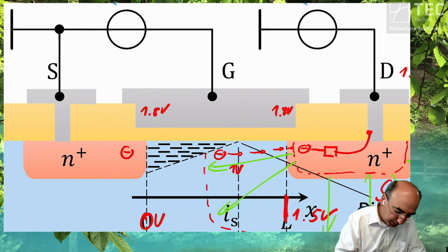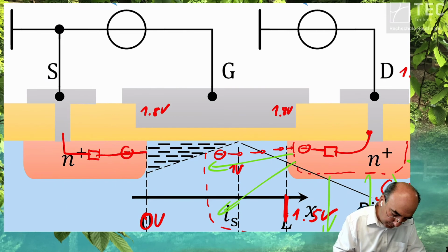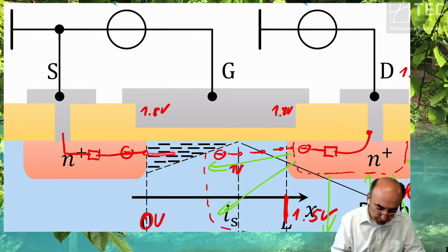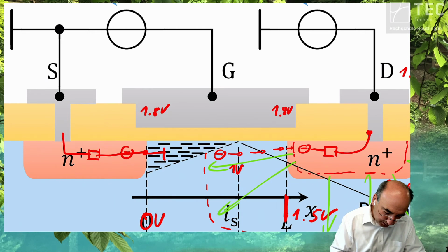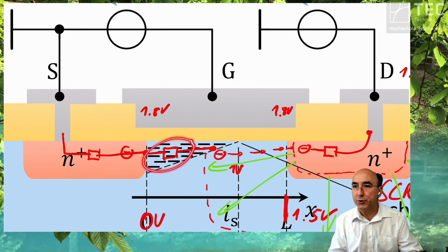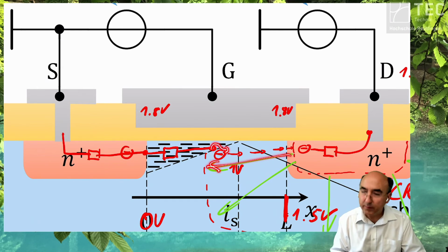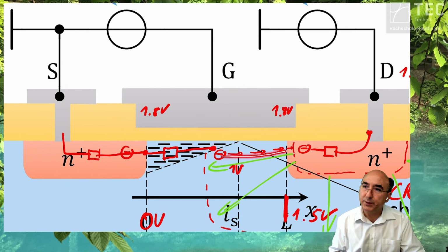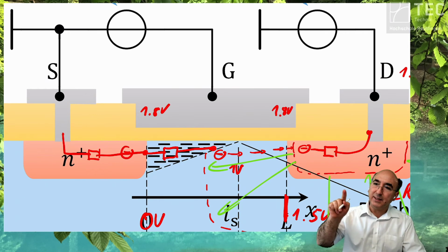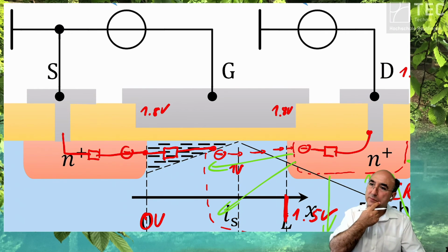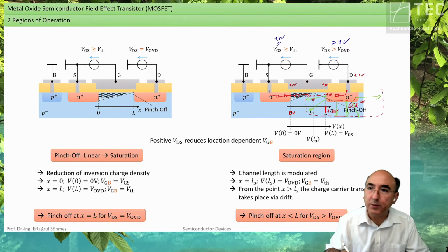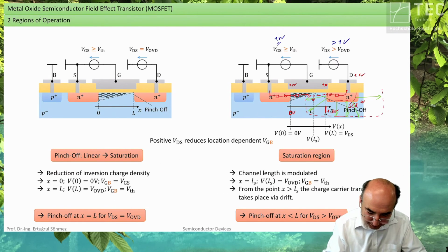That's it. That means you have an electron here. We have a parasitic resistance here. This parasitic resistance just changes to be an inversion layer resistance. So an inversion layer is also a resistor full of electrons. And the electron which happens to enter this electric field drifts through the electric field to this contact. And exactly the same happens in the PN diode. Where does that happen?